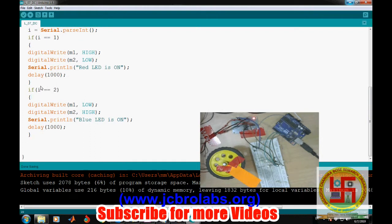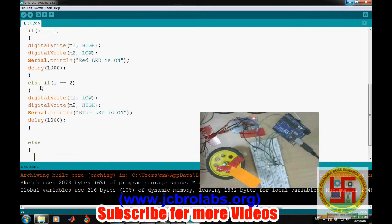Now we can make it so that if something else has been sent, it should stop. If any other thing is sent besides 1 or 2, then we should stop the DC motor. In order to stop the DC motor, it is very easy. We should make either both the pins high or low, then both the pins of the DC motor will be at the same potential and it will not move. So we will write low at both the pins in this case.